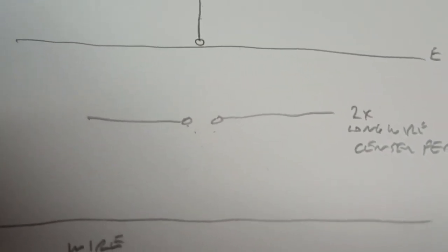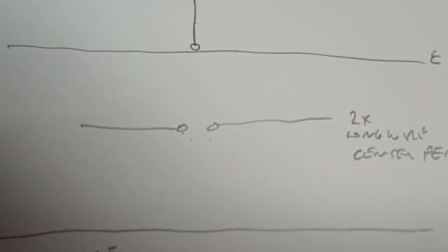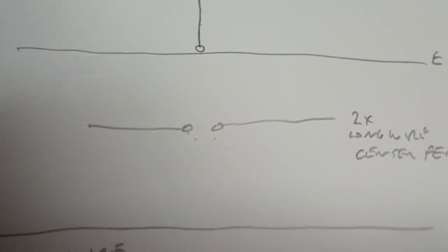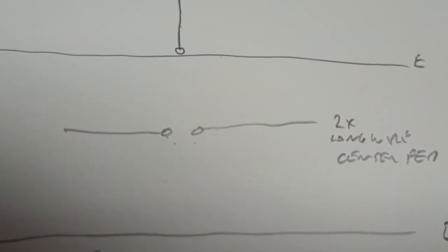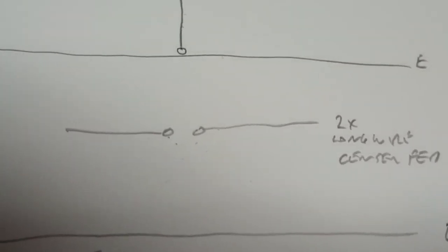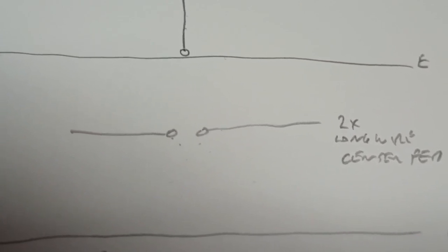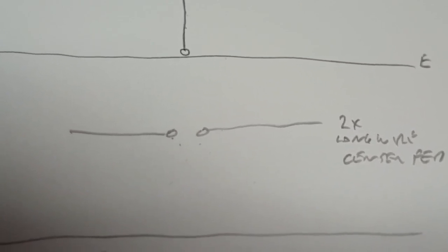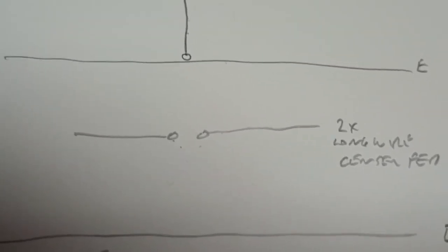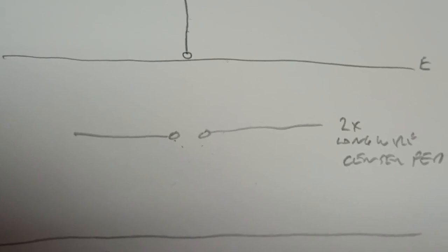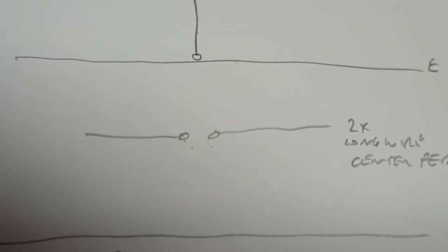That's what happens here. I made field strength measurements at low power on my 20-meter dipole. Nothing at the feed point, nothing until the ends of the wire. So that shows that the purpose is not initially for the antenna to couple to the ground because the energy hasn't reached the antenna yet. It's still coming into the feed point. So this shows that the feed point is distinctly separate from the antenna, and it is part of the transmission line, not the antenna.